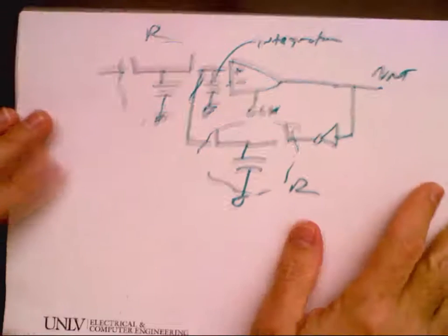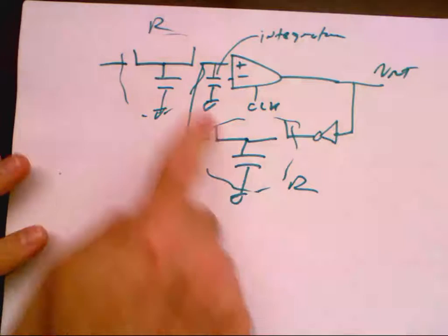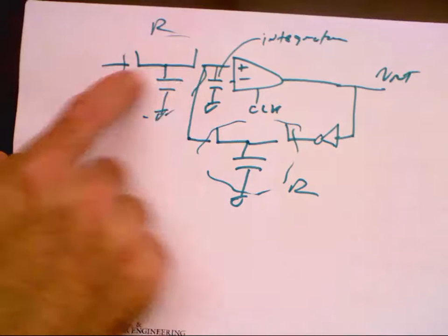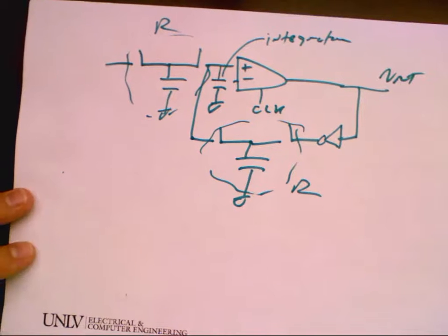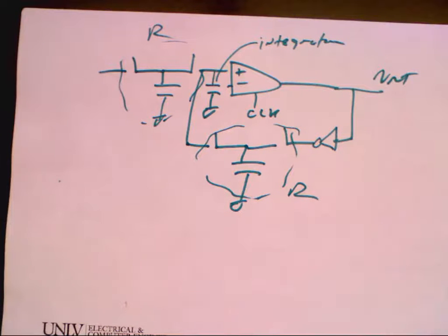So the idea here is since you replaced the resistors, if you look at it statically, you're not dissipating any power, right? Because there's no place for current to flow. So you have your clock frequency running back and forth. If one switch is on and one switch is off, after you transfer the charge, you're not dissipating any current. So I can design a modulator that could be used for remote sensing applications powered by ambient light or something, because it takes so little power. So I wanted to go through this topology. I want to modify it a little bit, and I want you all to help me derive the transfer function.